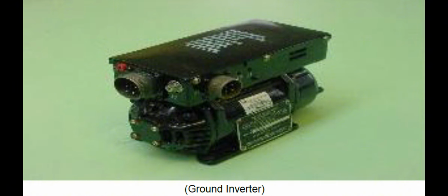Inverter power relay. The inverter power relay is mounted on the left attic compartment shelf. The relay is a single-pole contactor and applies DC power to the ground inverter. When AC power is not available at the primary AC bus, the inverter control switch is placed on. 28 volts DC from the primary bus is supplied to the solenoid of the inverter power relay, energizing the relay and applying 28 volts DC power from the primary DC bus to the inverter.